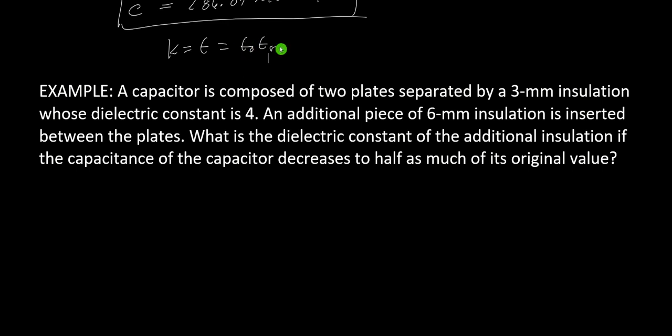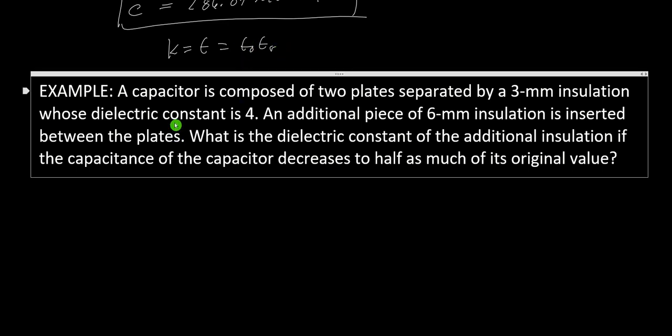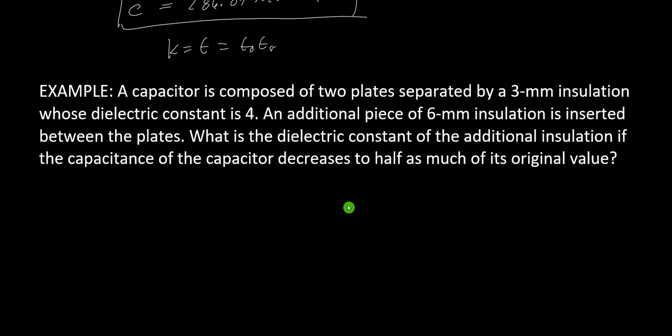That's constant. And it says this is a dielectric constant of 4. So this is somewhat contradicting. Sometimes we call this one the dielectric constant, but actually this one is the permittivity of the medium with respect to the absolute permittivity epsilon naught.